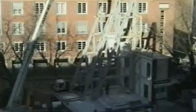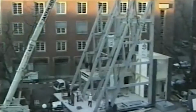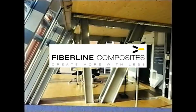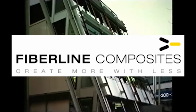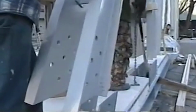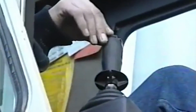Composites can weigh as little as 20% of the weight of stone or concrete cladding. This means a substantial reduction in the dead load of a building. Shown here is the Eye-Catcher building, constructed in 1999 by the Fiberline Corporation of Denmark, one of the world's leading manufacturers of PFRPs. The Eye-Catcher building was constructed for a trade fair and later disassembled and reconstructed at a new location. Reduced weight means smaller crane requirements and easier erection.